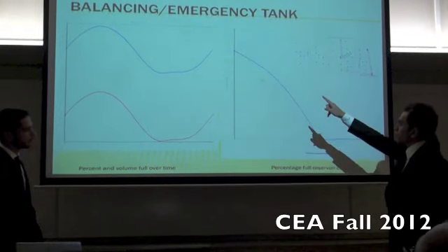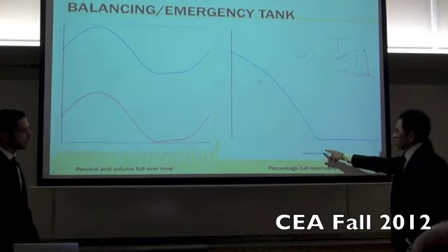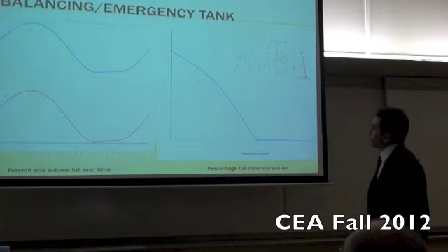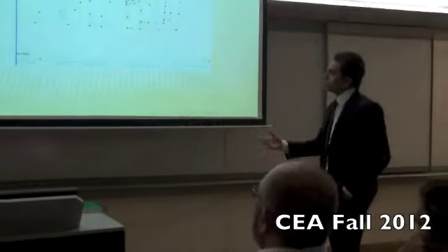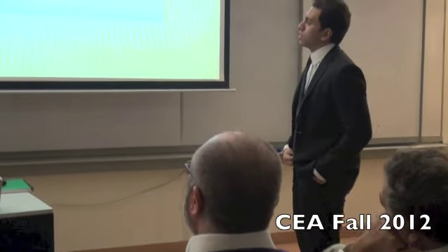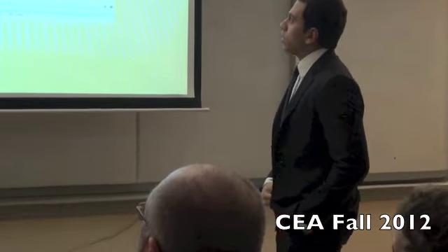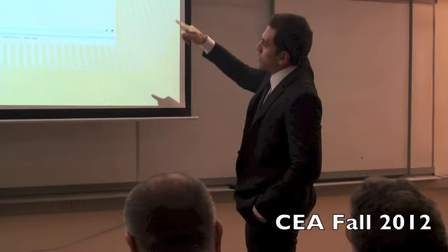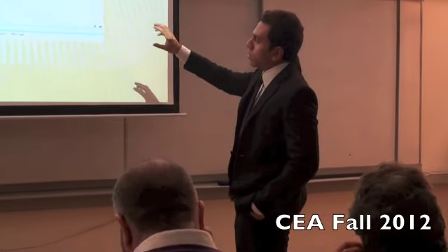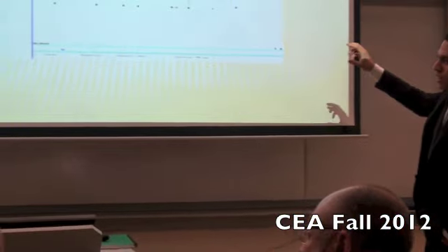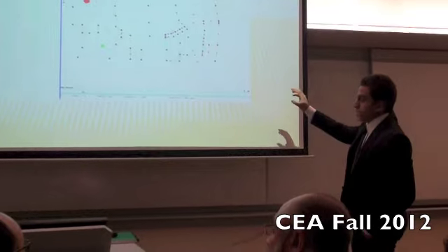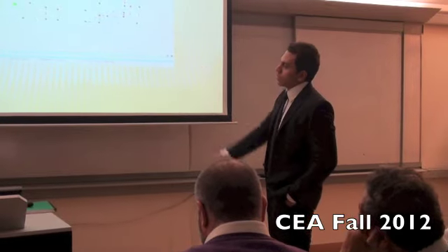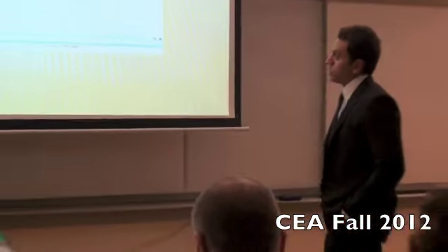As you can see, if the tank is full to 100%, it can supply the compound for almost 12 hours. And we also did a fire flow analysis on this model. The fire flow analysis takes the fire demand at all junctions and tests the model for certain conditions, like the residual pressure should be maintained not less than 2 bars, and it gives a result saying pass or fail.